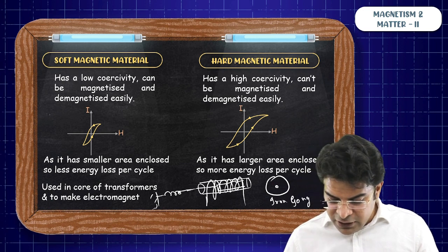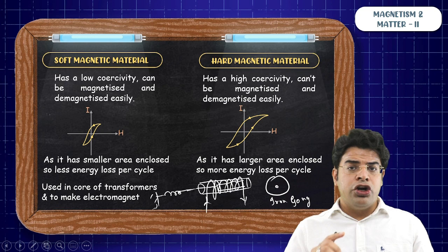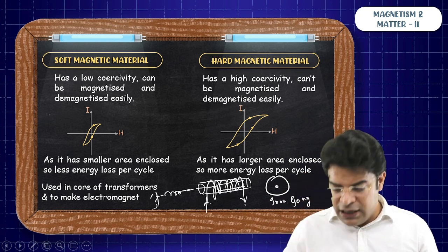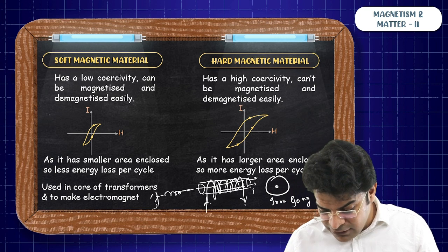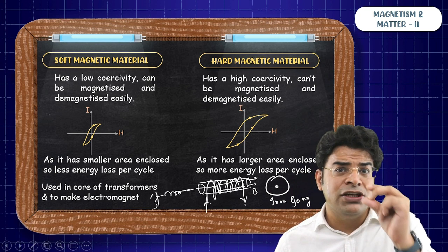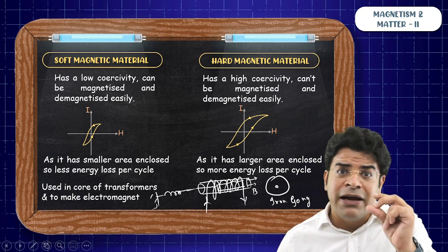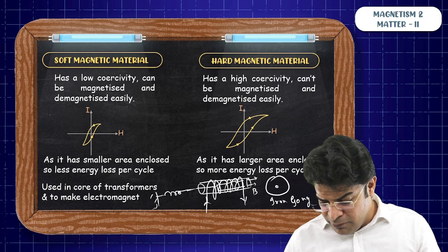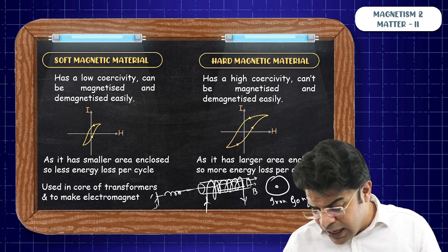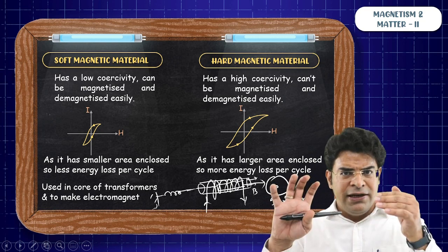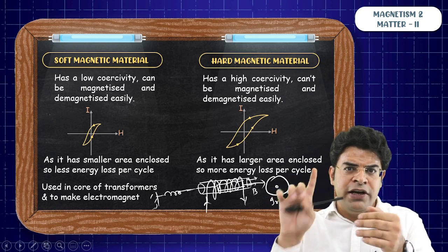When we drive the current in the solenoid by pressing the bell, a magnetic field is developed. This is a ferromagnetic substance inside the solenoid, so it gets magnetized very easily. Once it gets magnetized, it is attracted towards this iron gong and it goes and hits it. Once it hits, we get the sound of ting tong.